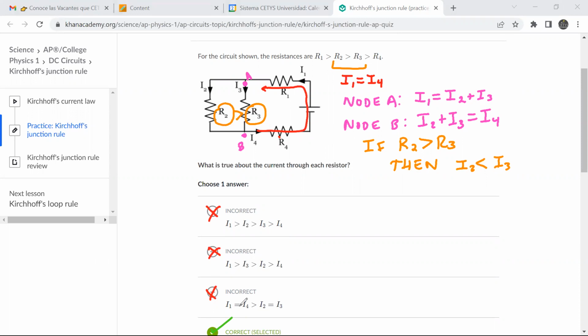So yeah, in series the current is the same. The way to remember it: in series the current is the same until the current is separated or divided. And Professor, if we didn't have that point about the resistors, if we assumed that they were all the same, would C then be correct? Could be correct, if we assume that the resistors are the same, yes, because the current would be divided equally.